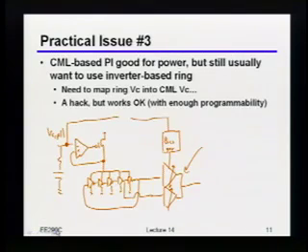Okay? The other thing you will do, because as I said before, this is a hack, is you'll very commonly put something inside of here, which is some sort of programmable divider or offset or something like that. Okay? Now again, here's where the hack really comes in. What you'll typically do is you'll just have something that says, oh, I know I'm in this version of the process, and roughly speaking, there's this divide ratio that I need to make this thing work in this version of the process. Okay? Again, this is a major hack, but the good news is, in practice, it mostly works. So, most of the time you can find a wide enough range of things that it works reasonably well. Okay? Does this make sense to people?